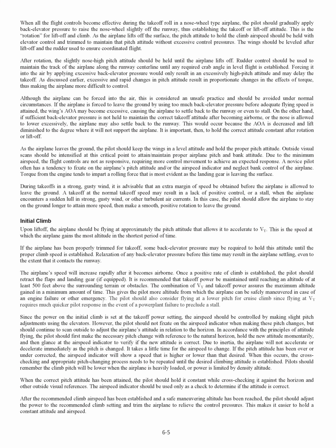If the pitch attitude has been over or undercorrected, the airspeed indicator will show a speed that is higher or lower than that desired. When this occurs, the cross-checking and appropriate pitch changing process needs to be repeated until the desired climbing attitude is established.